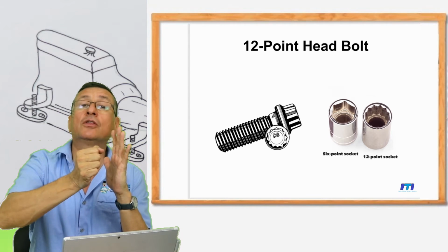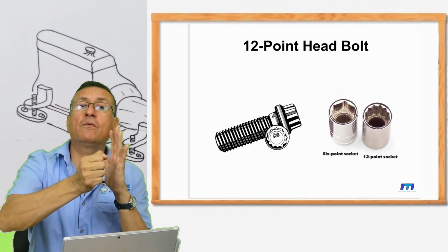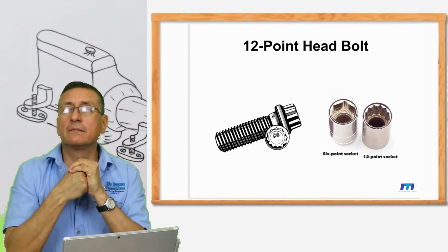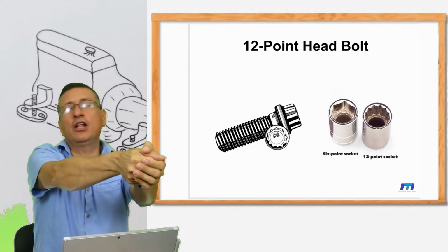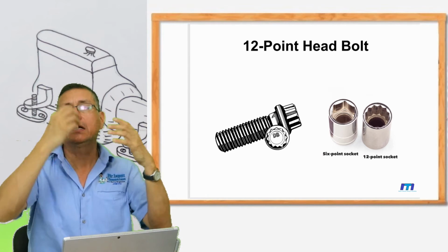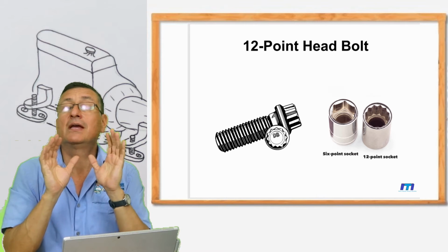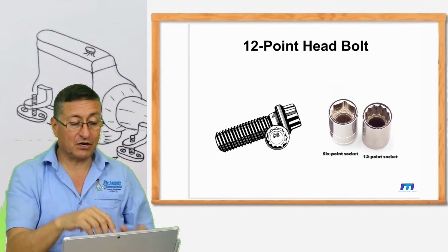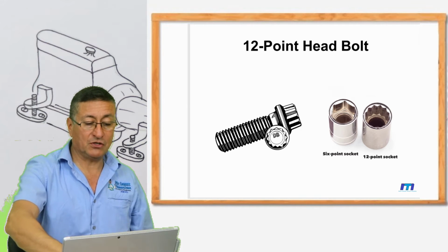Now you apply the torque slowly back and forward until you feel that the bolt starts to move. Do not try to apply all the force at the beginning because you ruin the head of the bolt. In this business, you need to be most patient, like we are going to explain with Mr. Rodriguez in the next coming episodes.